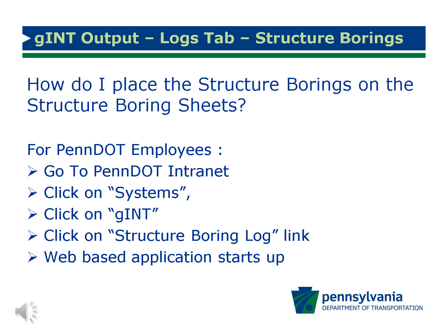For PennDOT employees, an internal application is available for placing structure borings on the structure boring plan sheets. Go to the PennDOT intranet, click on Systems, and then on gINT. From there, PennDOT users should click on the PennDOT Structure Boring Log Report Builder link to open the application.